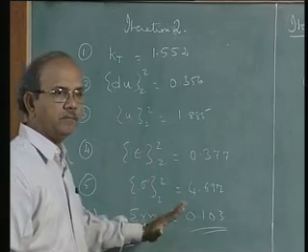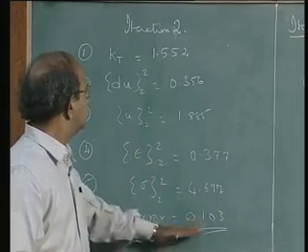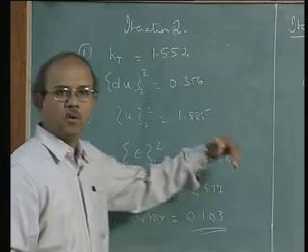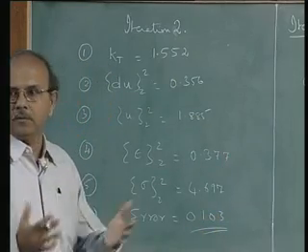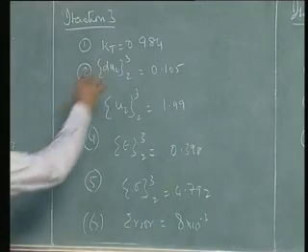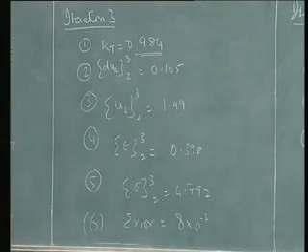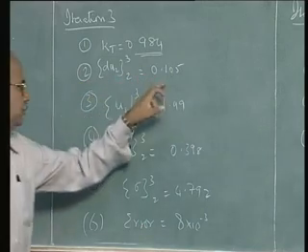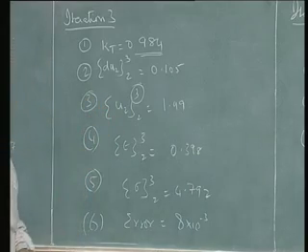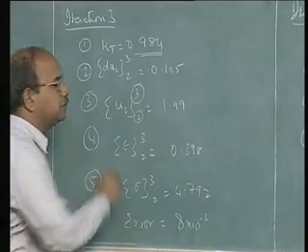Then we go ahead from iteration 2 to iteration 3 using the error to be the load or the right hand side. Remember, that's what we did. So now what I do again is to calculate this stiffness matrix. In this case it happens to be just one number because of the type of problem we are doing, and then we calculate du2 for the third. Look at that, it is the third iteration for the second increment.